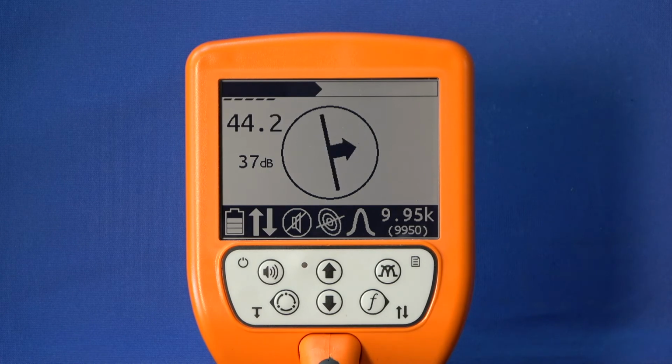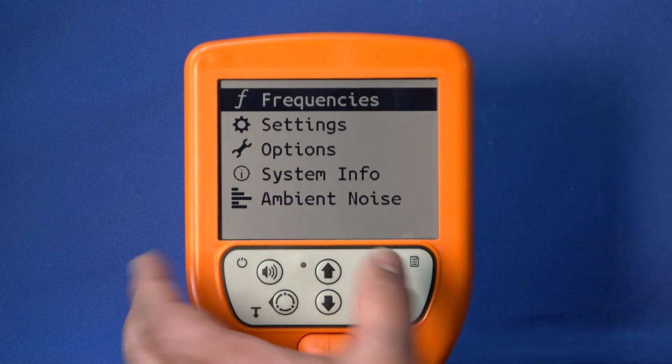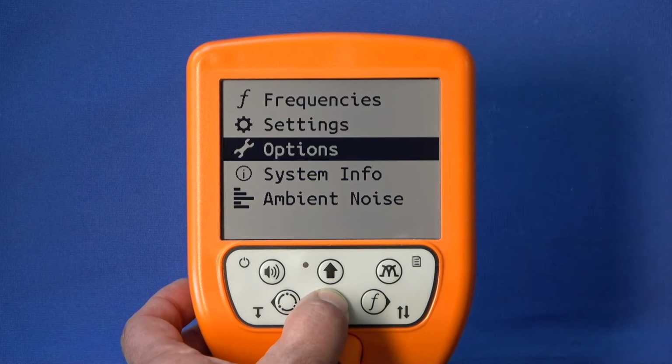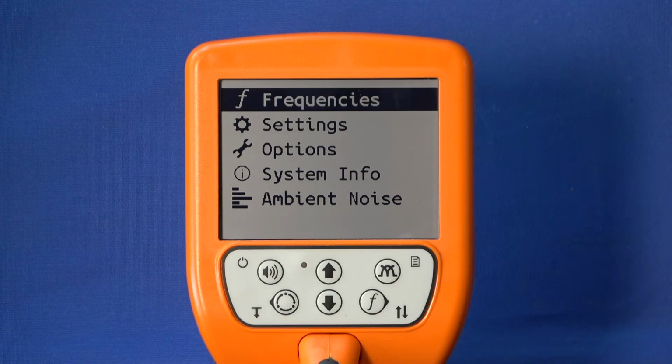You will find basic setting options for your UT9000 in the device menu. Press the signal behavior key for 2 seconds to enter the device menu. There you will find various submenus. Use the arrow keys to navigate through the device menu. The selected submenu is displayed inverse. You can select submenus with the frequency key.